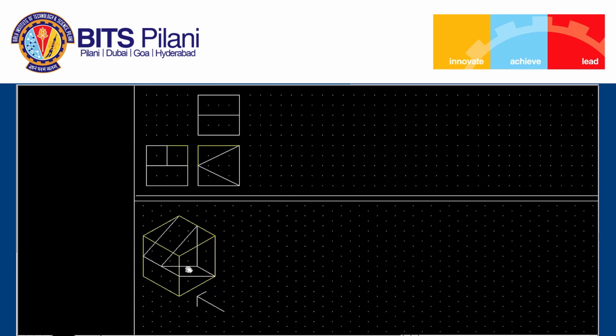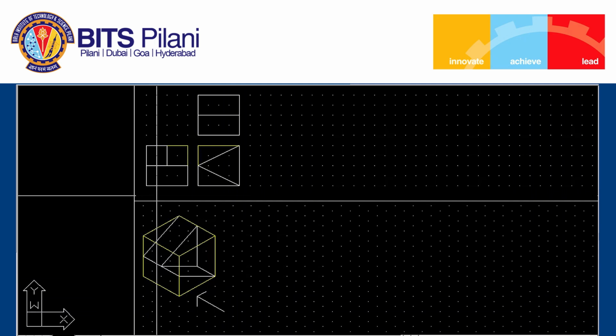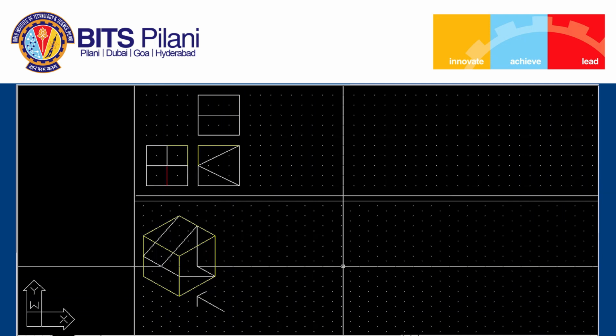Now what about this inclined surface? This is a surface, the point I can identify, this particular point in the side view, it is here. However, this surface is not visible. So what we can do, we will show it with the hidden lines. In our drawing, we will indicate hidden lines with the red color instead of changing the line type, because it is easy for identification. Wherever the red color is seen in the drawing, that means it is a hidden line. That color code we follow throughout the course for orthographic projections.